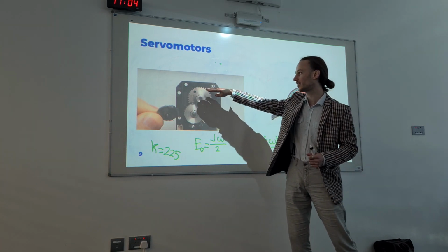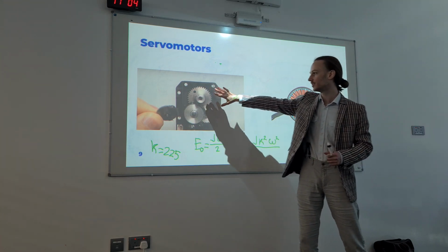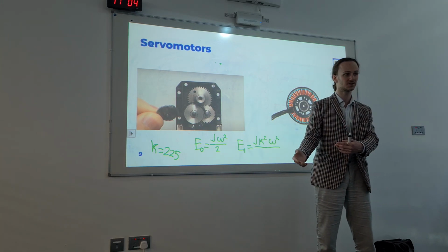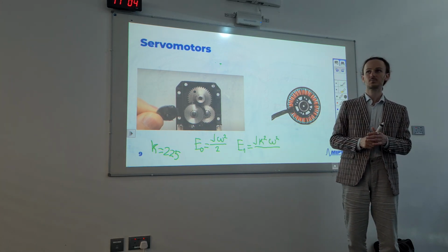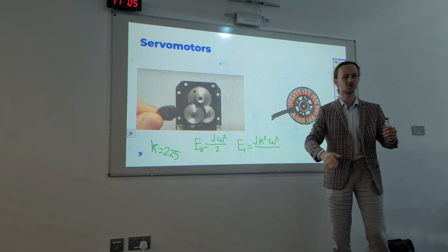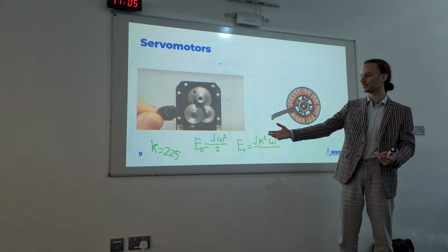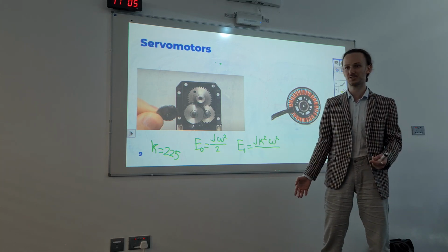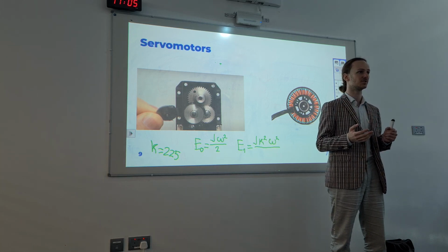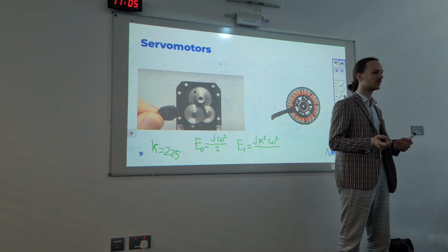So we're applying torque here, and we want this gear to rotate with a certain speed. Actually, we have to start rotating the rotor in the same direction for the whole servo motor not to try to stop the leg. It has to bounce slowly, not be rigid. And because of this gear ratio, it is not possible. During heavy impacts, these servo motors are pretty much rigid, so they just take the hit, and that's it. That's why they're rigid.